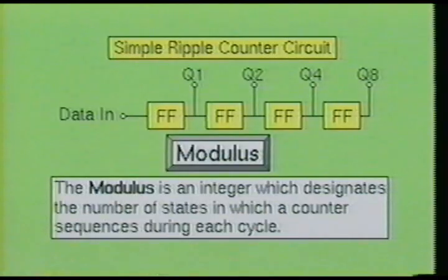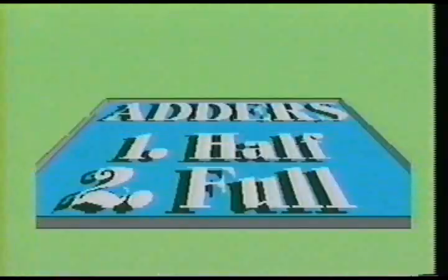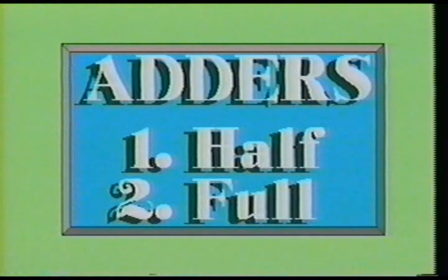So far, you have seen how flip-flops may be connected to count from 0 to the modulus number, or from the modulus number to 0. The modulus is an integer which designates the number of states through which a counter sequences during each cycle. But what happens if there are 2 numbers to be combined within the system? After all, this is what the computer does best. This simple combining of numbers is performed by circuits referred to as adders. As you shall see, there are 2 basic adder circuits. These are the half adder and the full adder.